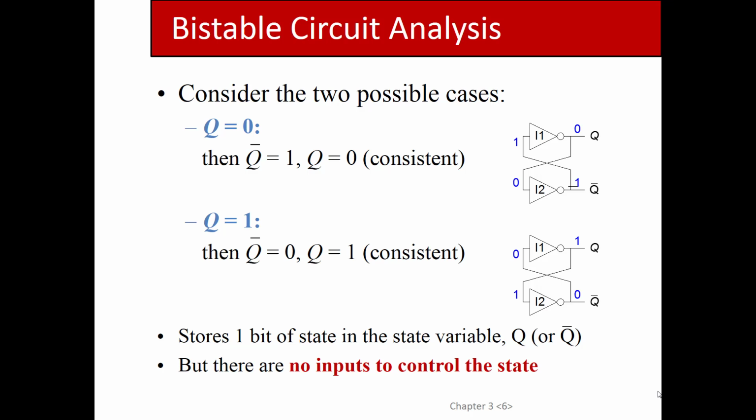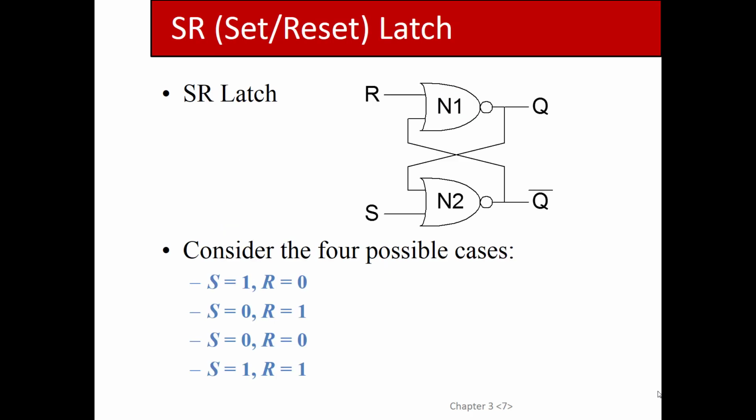Well, the thing about a NOR gate is that if I cross-couple NOR gates and then allow the user to provide the second input in each of those 2 NOR gates, then if a NOR gate gets a 1 on one of its inputs, what does that mean? It means that it doesn't matter what the other input is, the output's 0, right?